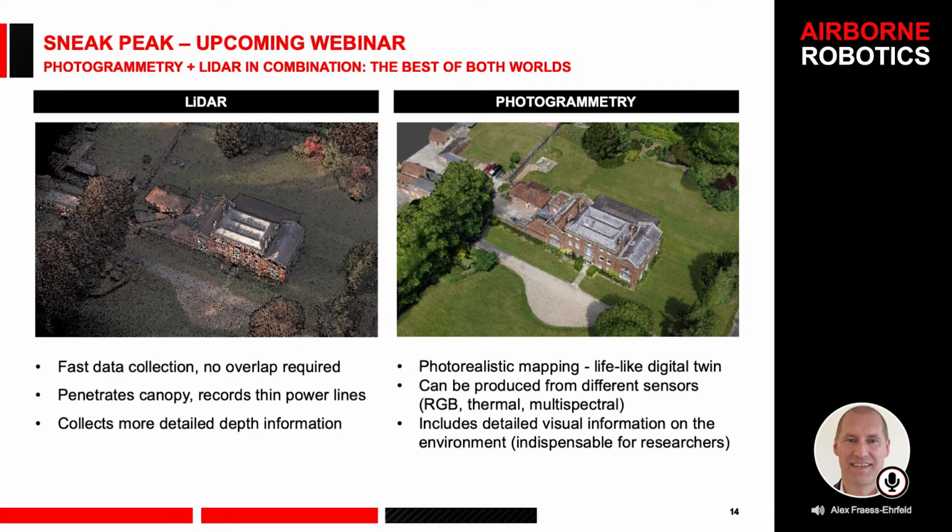You might have the first return, which plots the points on the surface, for example the tree canopy. And then the second return might be the ground. So you have a ground model as well as the model of the surface. That can be very valuable information, in particular when it comes to, for example, power lines, or the construction of rail, or the construction of cable cars.